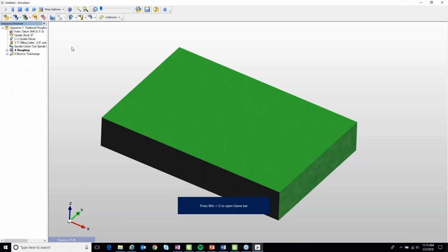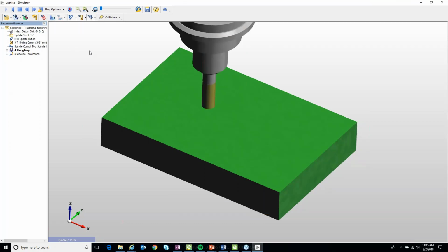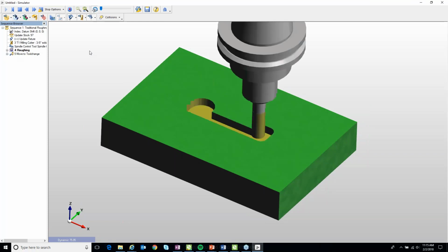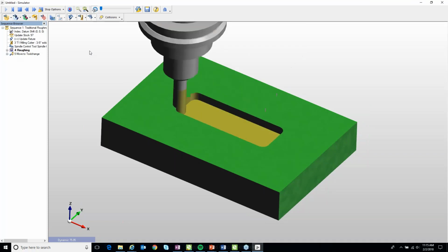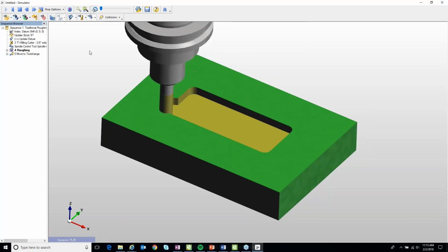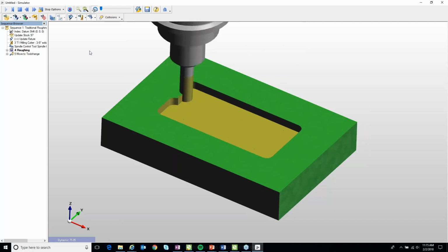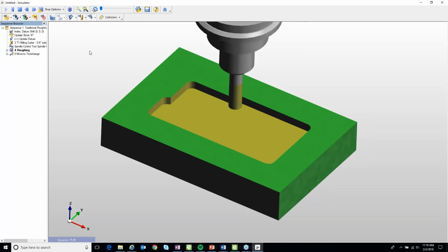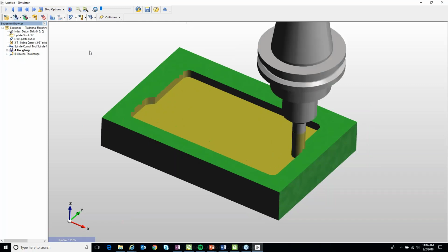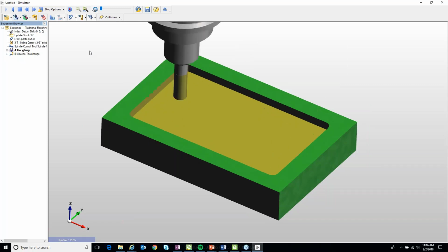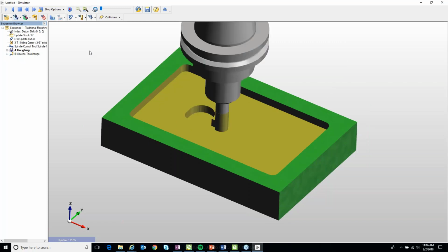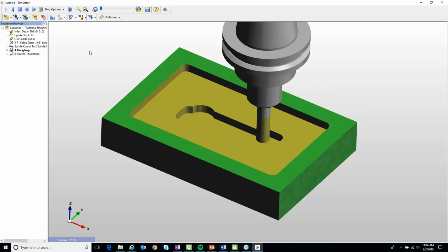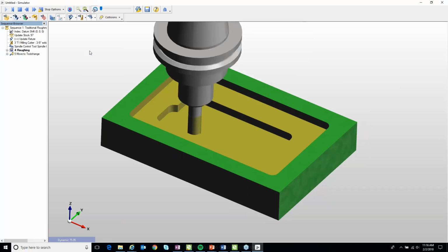As the tool comes into view, you're going to see this traditional geometric collapse start by helixing in, and then the big paths, which we know the tool is buried in, 100% engagement. As the tool then goes to machine the other areas, imagine what this will sound like at the machine. We'll hear the tool load changing significantly during the longer cuts where the engagement's pretty good, and then heading into corners where the engagement gets heavy, and the transitional moves between the geometric collapses where the load changes again, and in some cases the cutting direction changes a little bit abruptly.